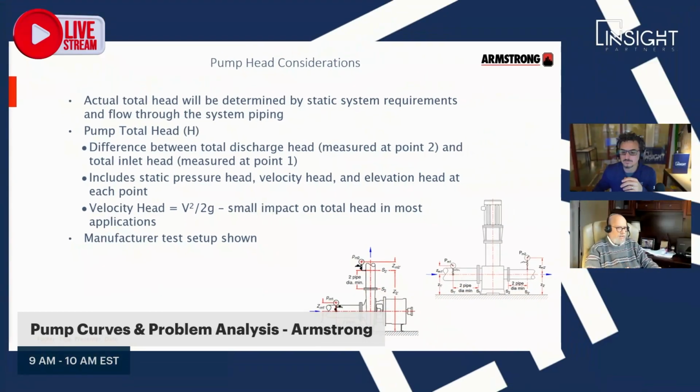And those two are additive in that case. So understand, it depends on whether it's an open system or closed system as to whether we're dealing with static or not. Velocity head really has a very, very small impact on total head in most HVAC applications. Now, I'm not telling you that it doesn't, but in most HVAC applications, it is minimal.